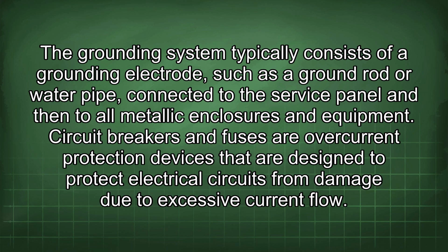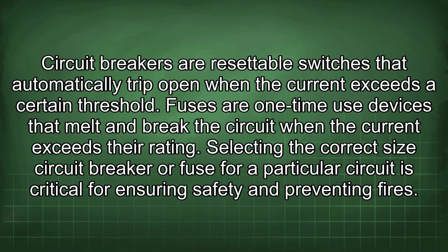Circuit breakers and fuses are overcurrent protection devices that are designed to protect electrical circuits from damage due to excessive current flow. Circuit breakers are resettable switches that automatically trip open when the current exceeds a certain threshold. Fuses are one-time use devices that melt and break the circuit when the current exceeds their rating. Selecting the correct size circuit breaker or fuse for a particular circuit is critical for ensuring safety and preventing fires.